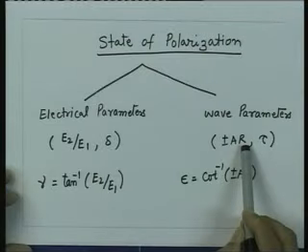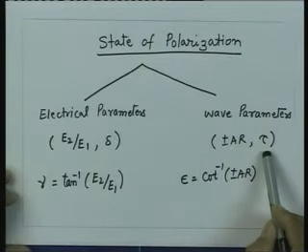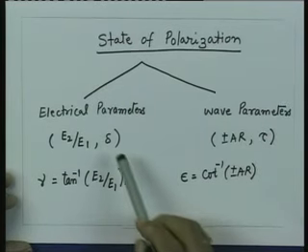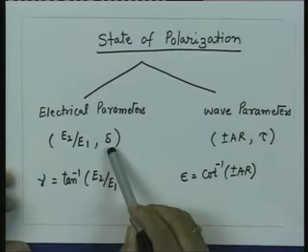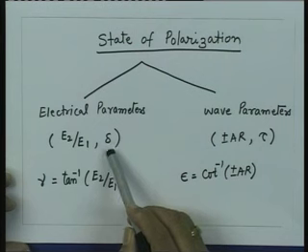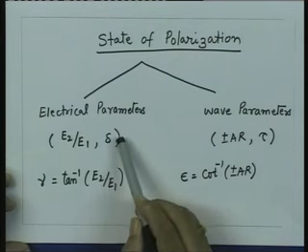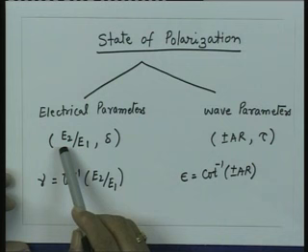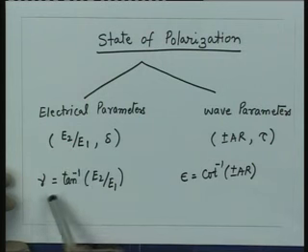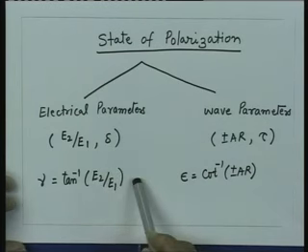So, now if I look at the ellipse of polarization, we have the axial ratio which ranges from 1 to infinity. The tilt angle will vary from 0 to pi. The delta, which is the phase difference, varies from minus 90 degrees to plus 90 degrees if we take the sign absorbed into the amplitude, and then this angle gamma will vary from 0 to 180 degrees or minus 90 to plus 90 degrees. So, we now have the range for all these parameters.